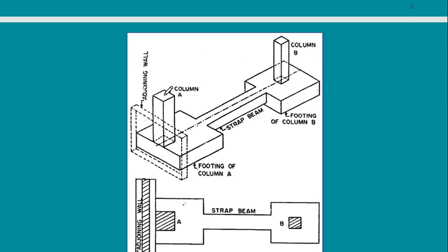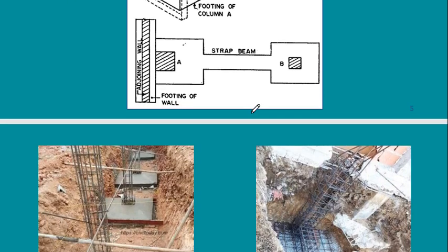In this case, the column is not in the middle of the wall. And you know from a previous lecture for isolated footings that the CG of the column should coincide with the CG of the footing. Otherwise, I will have moment, and if I have moment, it means that this column is about to overturn. We'll discuss this now.